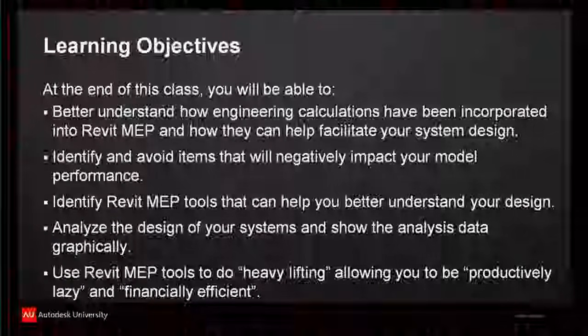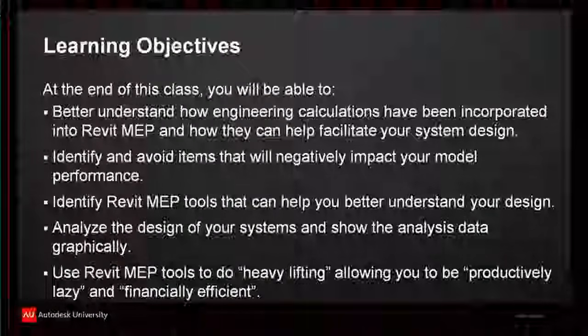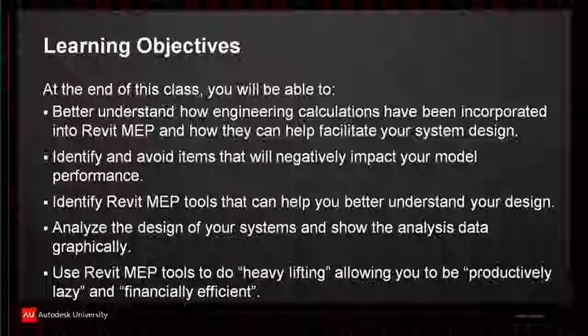We're going to talk about things that are going to negatively impact your model. So in order to use the calculations, you have to do some things within Revit MEP. You have to connect your systems. You have to watch out for warnings.